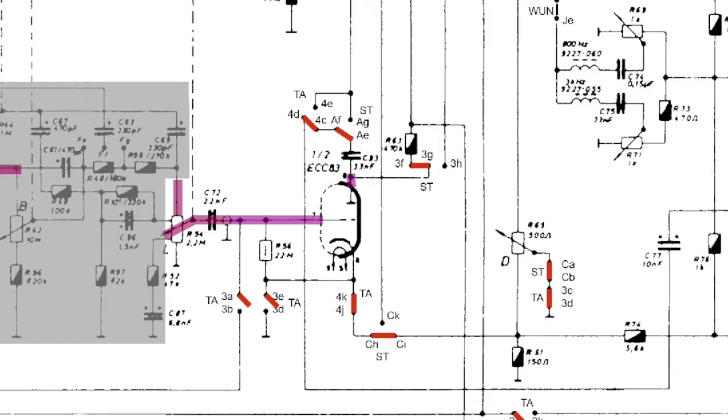That being the case, the signal that comes in here is amplified. It's actually inverted, but it then comes out here through that 3.3 nanofarad capacitor. It meets the switch, goes across the switch, and comes down here.